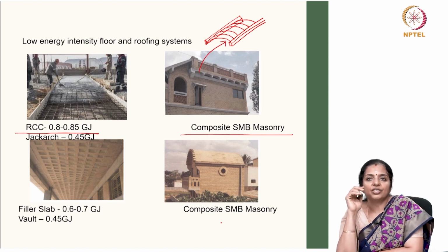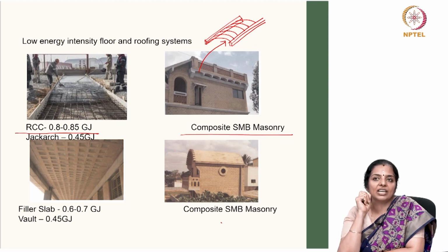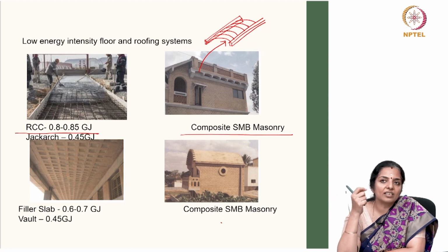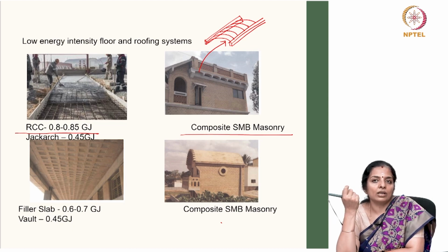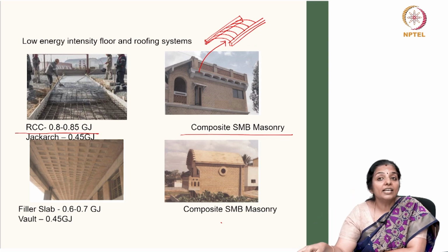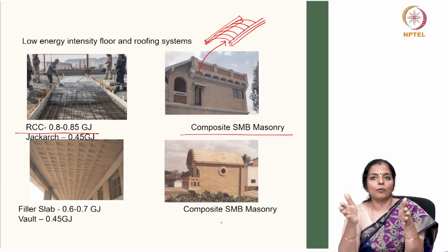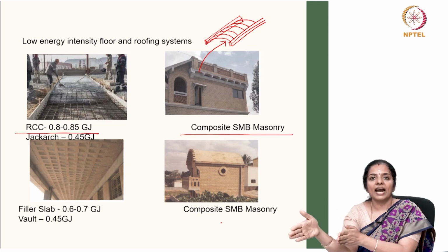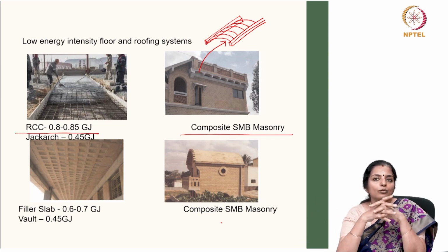So, this jack arch is classically defined as a structural element in masonry construction which provides support at openings in the masonry. Its other names are flat arch or straight arch. Unlike regular arches, jack arches are not semicircular in form. Instead, they are flat in profile and are used under the same circumstances as lintels. This name has also been used to describe another roofing system that involves a series of smaller sized yet elongated vaults that are supported on intermediate beams, and these are called jack arch slab roof type.